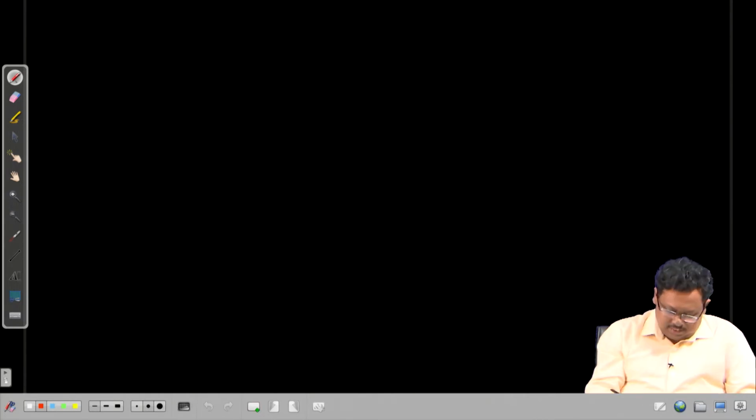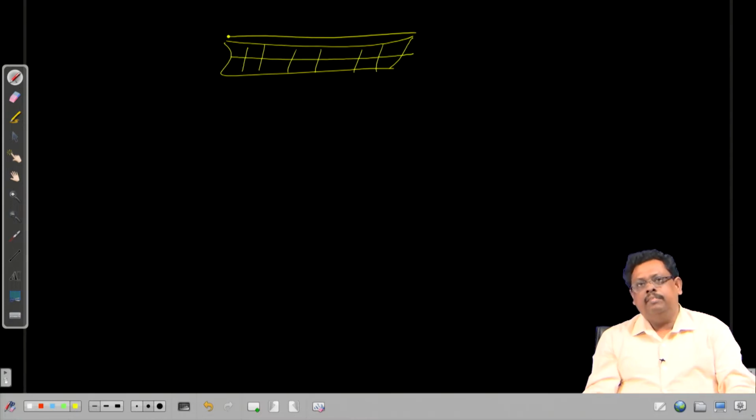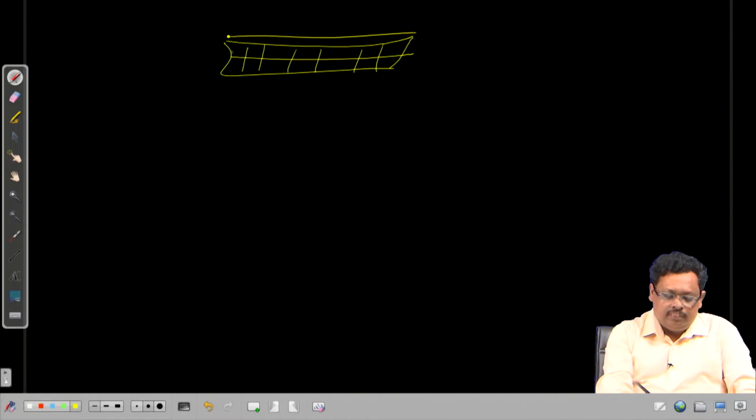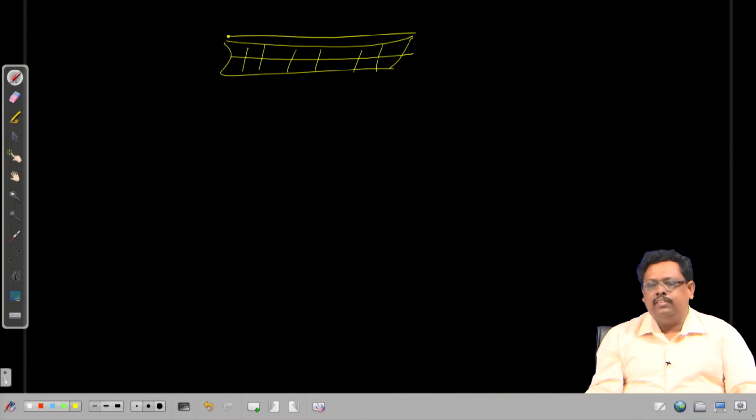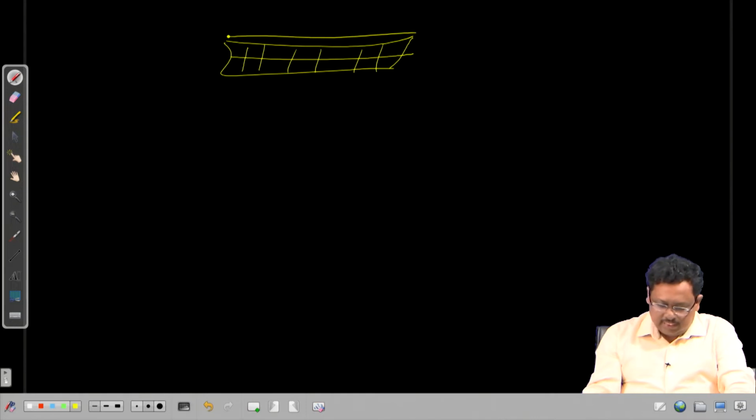For example, when you do the meshing on the ship, your input is the meshing. Therefore, you need to do quality checking of the mesh before you proceed. We discussed what can go wrong, what you should avoid, and what to check first, in the last class.